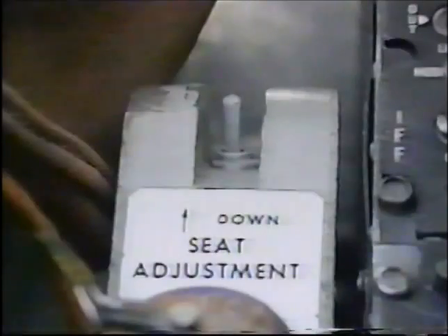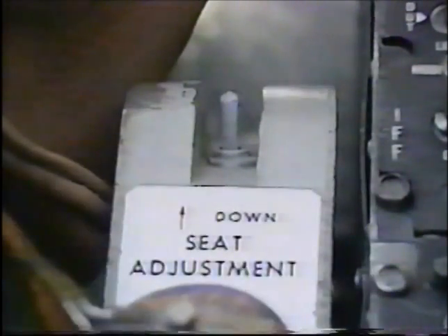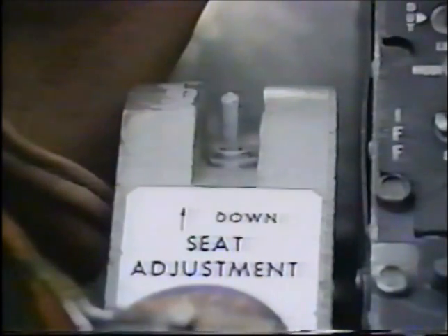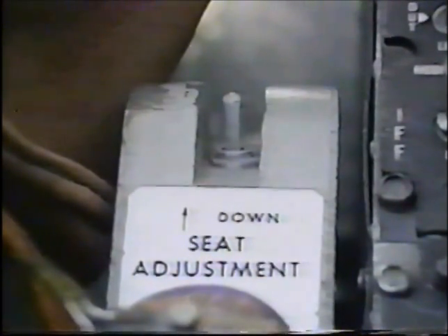Now check the crossover relay switch by turning the right generator off. You'll know if you have a good crossover if all right generator associated equipment remains on. If it looks good, turn the generator switch back on. Adjust your seat as required. As a technique, many front seaters lower the seat until the base of the pitot boom just disappears. Make sure your IP does the same.